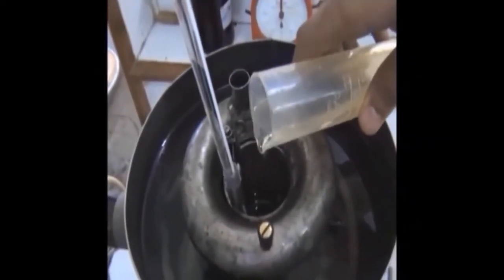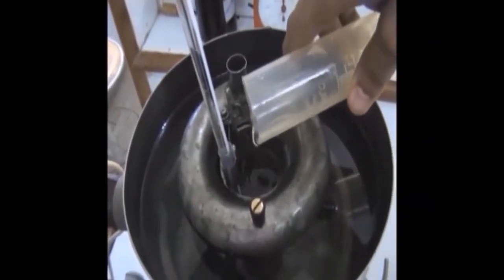Let's begin with the first part. Filling in the glycerine into the vessel, we start the heating. The first reading will be taken at 40 degrees. It is important to stir the water while heating, as mentioned before. As soon as the thermometer reads 40, the stopper should be taken out and simultaneously we